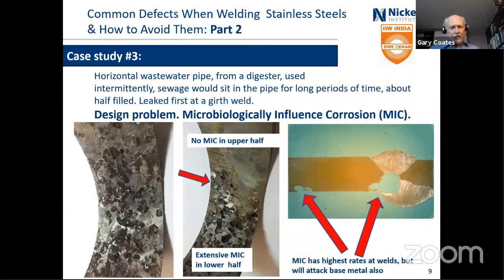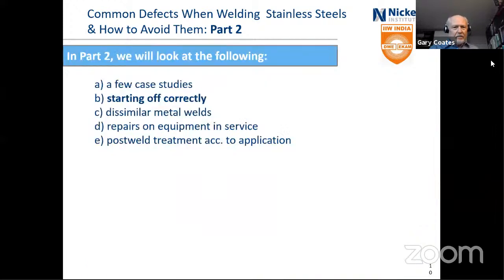Had nothing to do with the welder. It was a design problem. And what happened here is that they really should have flushed the pipe out. They should have put a spray nozzle in at the beginning of the pipe and then flushed all the solids out of the pipe, so there was nothing sitting in the pipe, and it would have been completely drained. So that is the issue there.